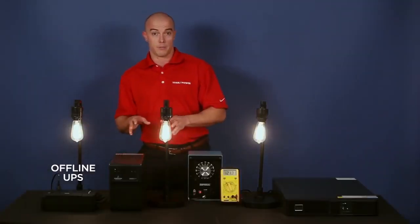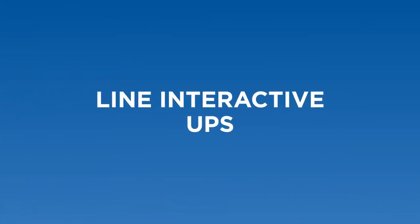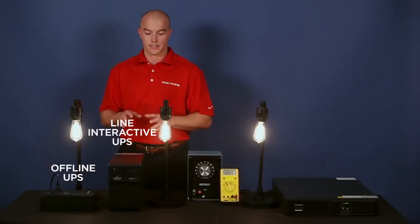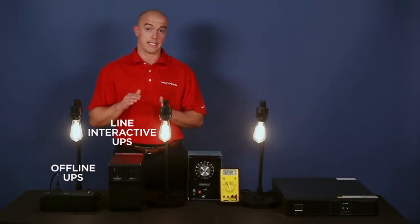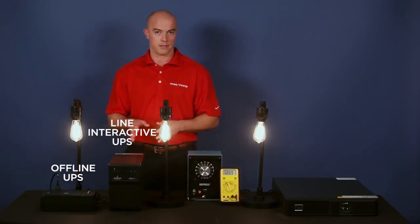The second type of topology, and the next step up, is a line interactive UPS. Line interactive, like the offline UPS, lets a few power anomalies through. However, it employs a buck boost transformer to manipulate the voltage into a tighter tolerance for more sensitive loads, while also preventing the battery from being used as often. This extends the battery life and decreases the cost to maintain this UPS over its lifetime.